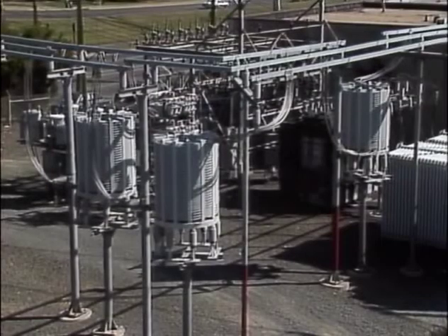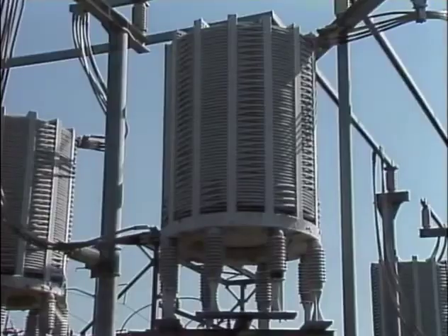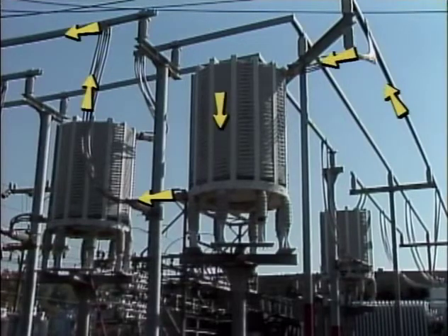A series reactor can sometimes look very much like an air core shunt reactor. A typical series reactor is an exposed coil. The turns of the coil are separated and supported by a non-reinforced concrete or epoxy frame. One of the main physical differences between a series reactor and an air core shunt reactor is that a series reactor is connected in series with a circuit. A series reactor is also known as a current-limiting reactor. This name suggests the function of the reactor, which is to limit current.